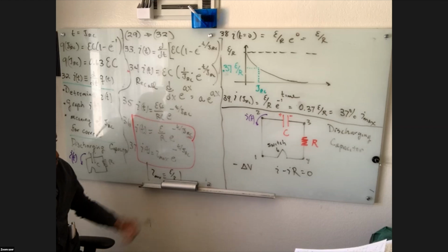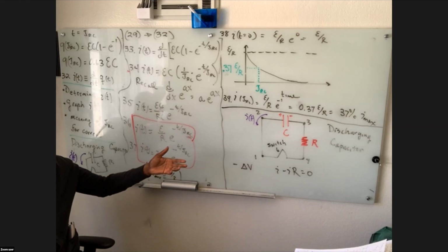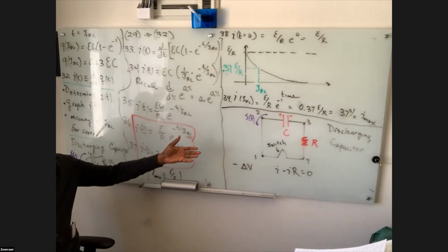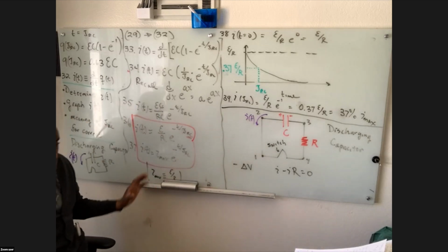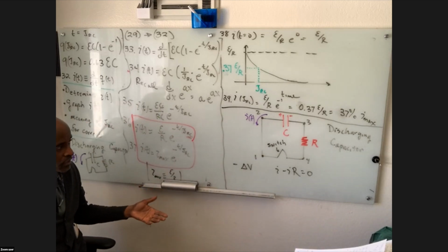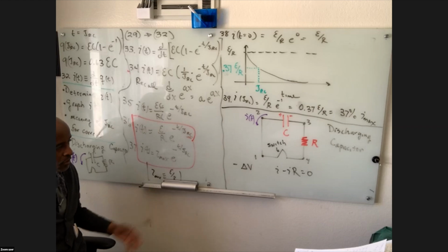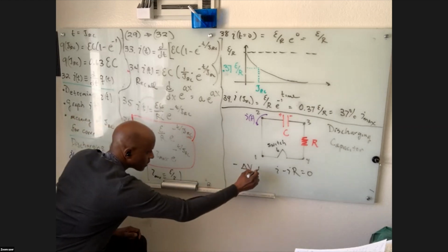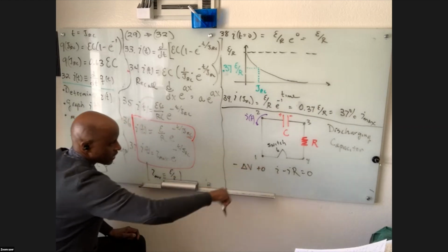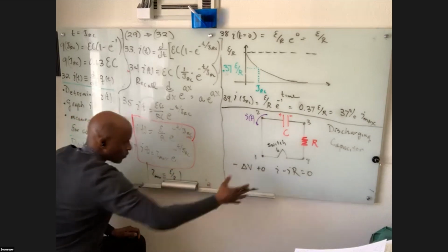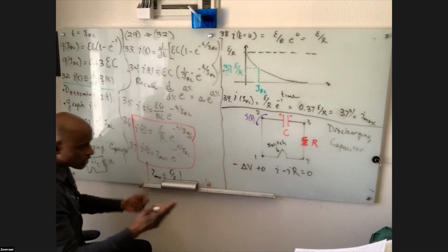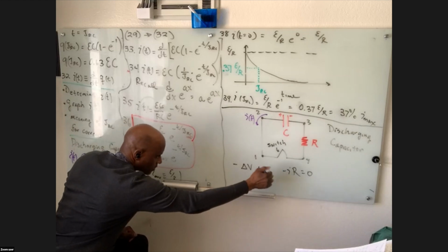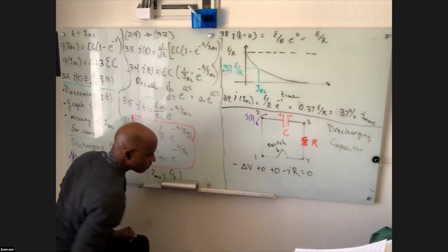If we did assume the wire was not ideal, there would be a voltage change associated with the wire. You would treat it like a resistor, and the voltage drop across that little point would be I times the R of the wire, not just I, but IR. But since we're assuming it's ideal, it's just zero. And the same thing for the other one. That's just the symbol for a switch. It's just off and on, like connecting the wires, really. So that's also zero.